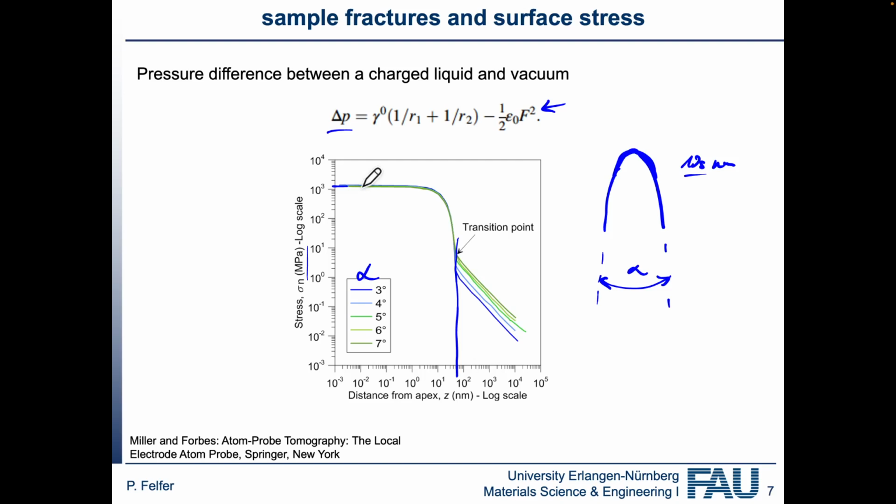Well, because they're nano objects. And so with nano objects, we're getting closer to the theoretical strength, just like if you have a nanowire. If this wasn't the case, then we would have the problem that all of our specimens would break. Of course, what we then don't know is, if we have any dislocations in there, for example, would the dislocations just get pulled out as soon as I put on the field? Effects like that are not necessarily known and they're a little bit hard to know.